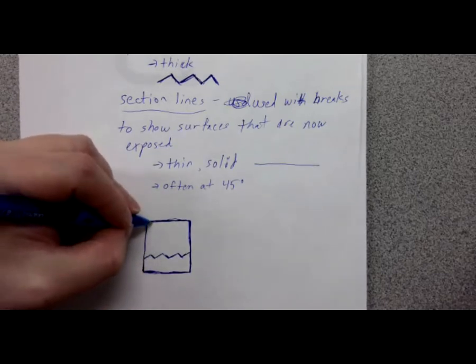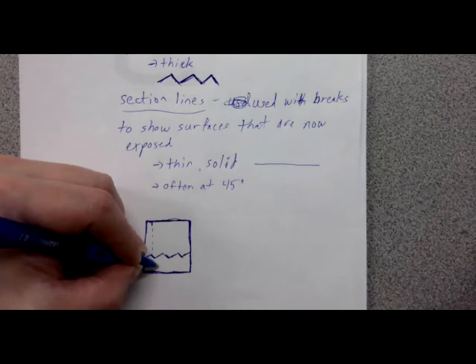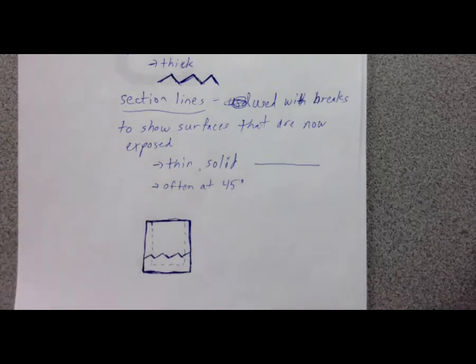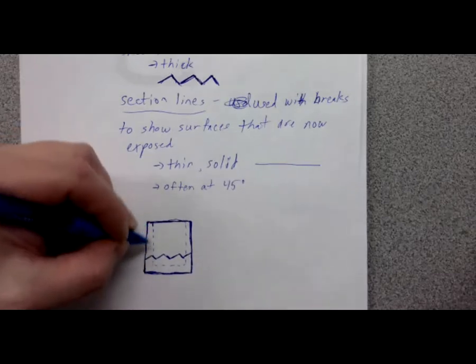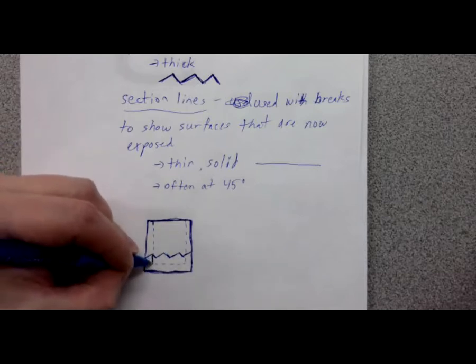And then what I can do is, whereas earlier, if I had thin lines, or if I had hidden lines, by the way, if you go ahead and dot the whole thing out, it's easier to go back later if you have long lines. It's easier to draw them in dotted, especially if you're on a pencil. You'll draw them in dotted first. You can always go in and fill in the dots later. But it's a lot easier to erase if you make a mistake. It's a lot easier to erase dashes than it is a solid thick line. A good solid thick line is really hard to erase, if not impossible, depending on how hard you press. But a dash line like this is your initial rough pass. It's easier to erase that if you make a mistake. Now here in this case, what I've done is I'm saying I'm going to cut away down here below this jagged line, this break line.